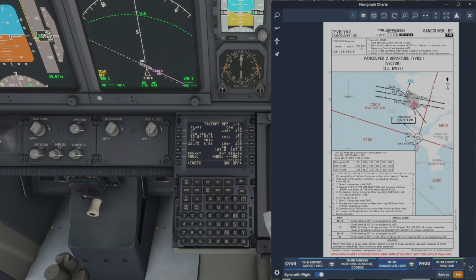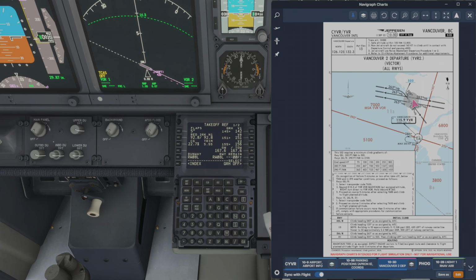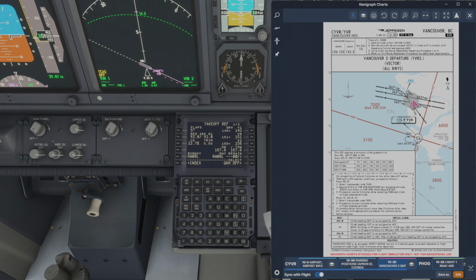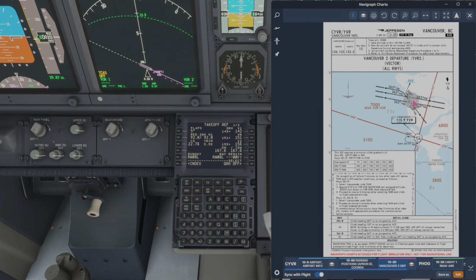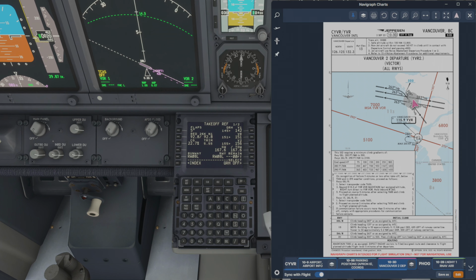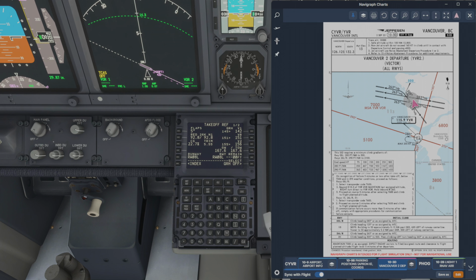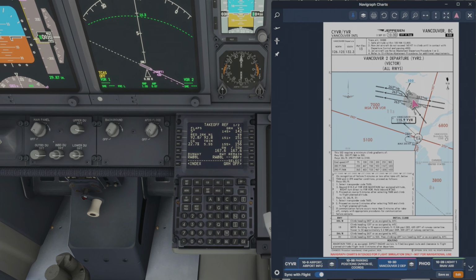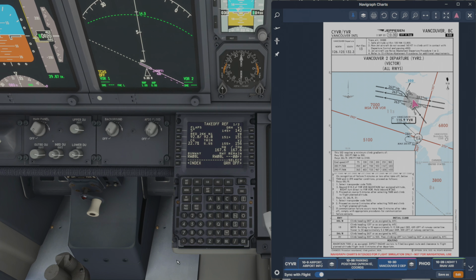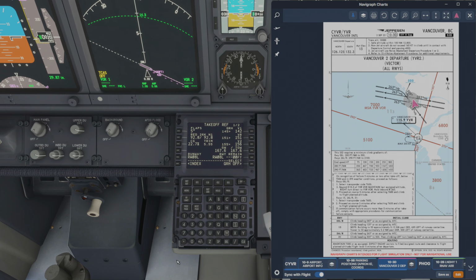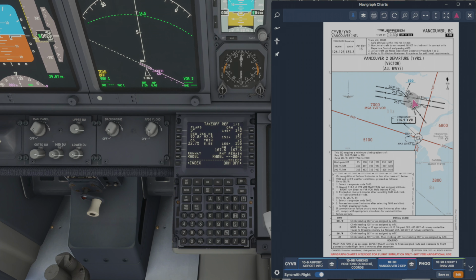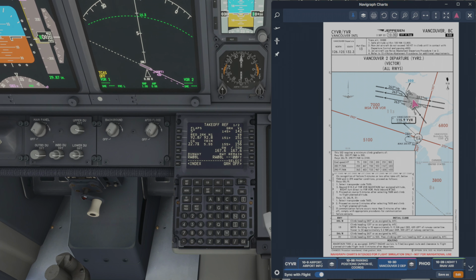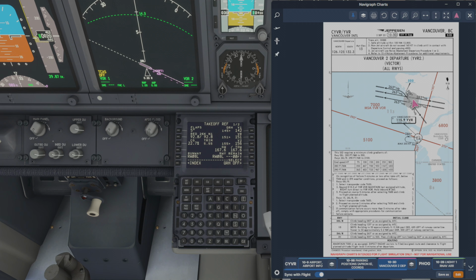And we are overweight, above our maximum landing weight here, so if we do need to return to the field ASAP, we'll do a pattern flight, and we'll land on 8 right. This will give us a longer landing distance. And we'll assess the situation in the air, and we'll coordinate with ATC. And that's it for the emergency brief.